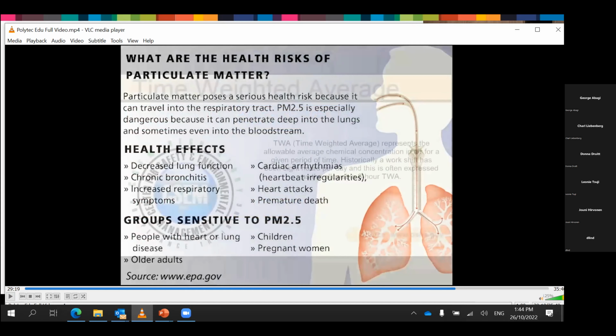So MDF, Australian-made medium density fiberboard, off the shelf is available in E0. E stands for emission, 0 is a level of gassing. Particle board off the shelf is available in E1. However, the Green Building Council of Australia have given same credit points for particle board and MDF.